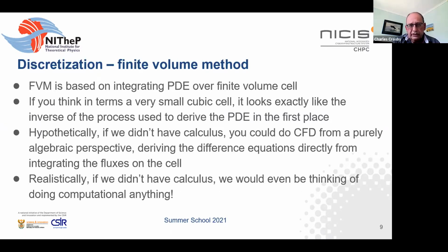So there's an interesting natural hierarchy of thinking in terms of cells. You're integrating that partial differential equation over a finite volume cell, but it looks a lot like the infinitesimal volume that you used in the first place to derive the partial differential equation. So you could do totally algebraic computational fluid dynamics.